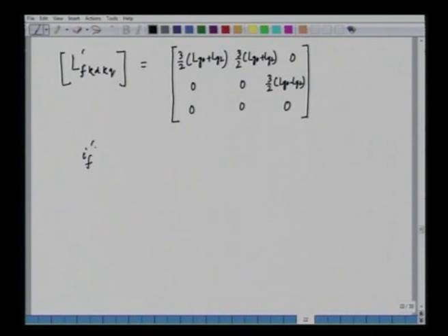Now by this special transformation, the currents of the rotors also get changed. The voltage of the rotor also gets changed, because we are referring everything from the primary side in the dq reference frame. Now the rotor current will be If prime is equal to 2 by 3 times Nf by Ns into the actual If. You can see that we have a factor of 2 by 3 coming, because the rotor is a two-phase rotor and the stator is a three-phase stator, and when we are transforming into the stator side, there is a 2 by 3 factor coming into the picture here.